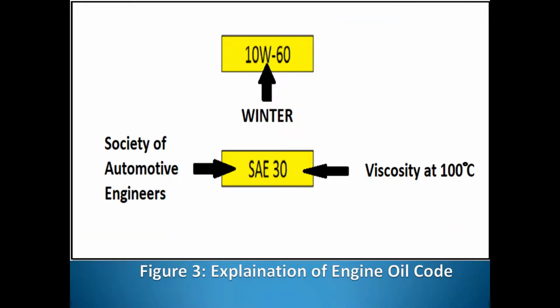Here I will explain about engine oil code. So for multi-grade, we will see W, that means winter. And then for the monograde, SAE stands for Society of Automotive Engineers. And this viscosity value are taken at 100 Celsius.